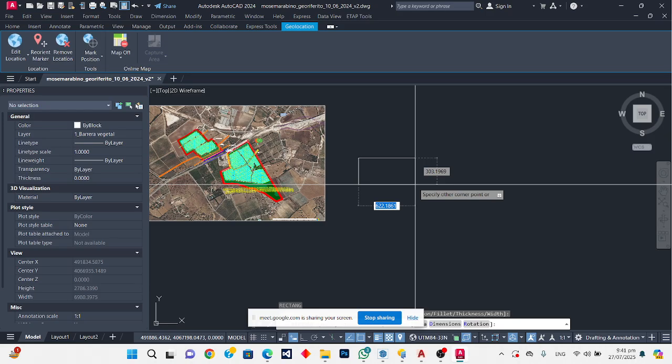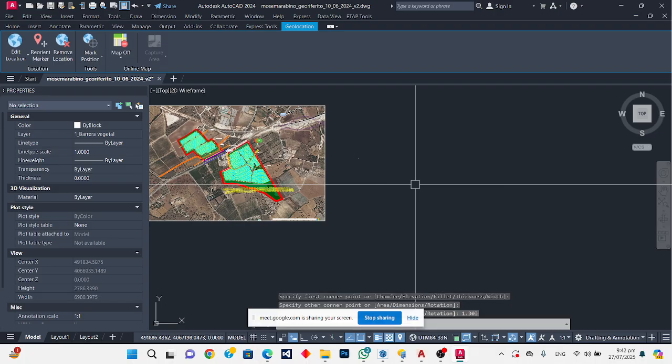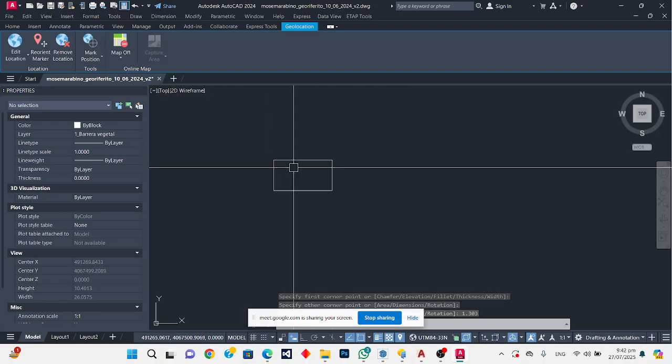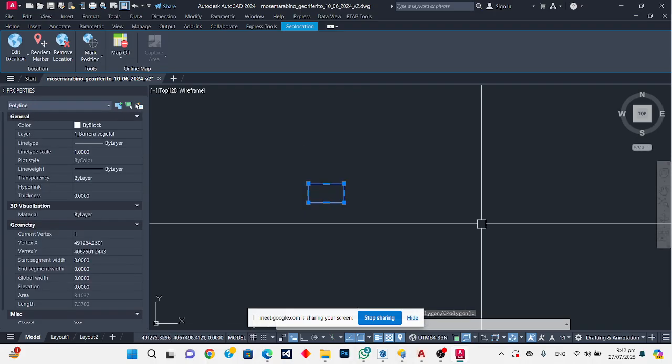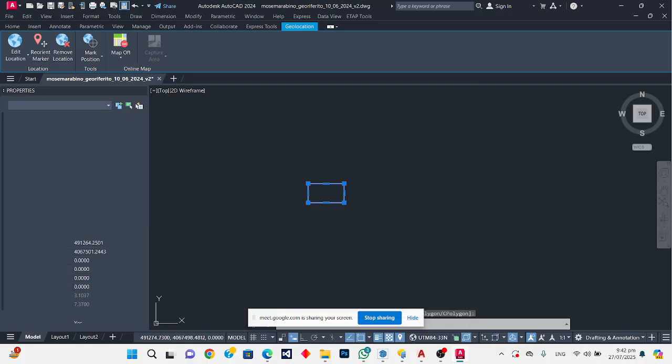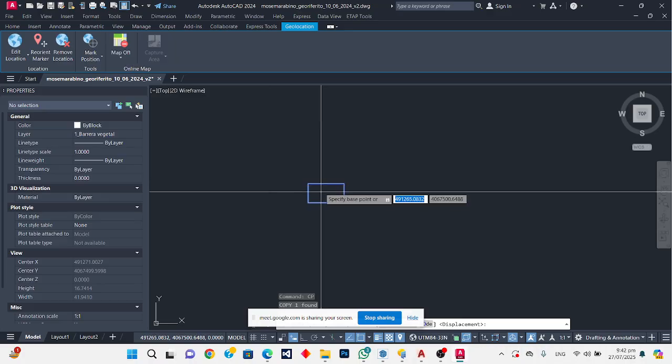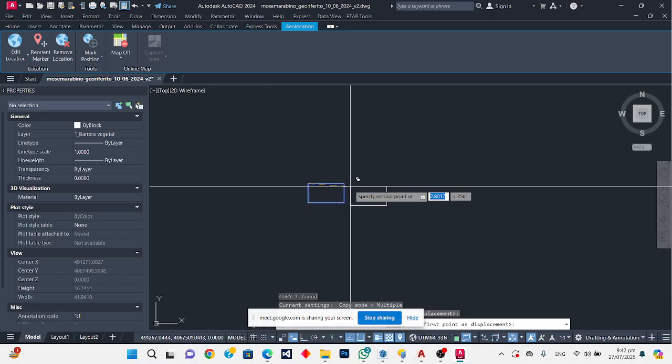You see that I have selected the rectangular command in AutoCAD, and here it is in meters. The length of the module is 2.382, and the width of the module is 1.303. It is a small PV module. You see that I have built it, and you can select this option and use CP for the copy command, and select from that and place it here.